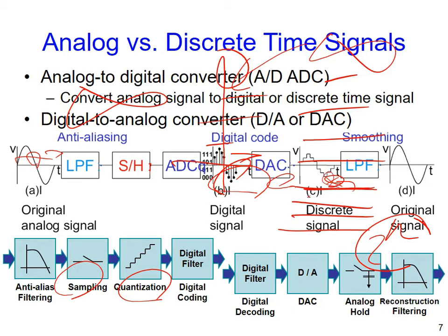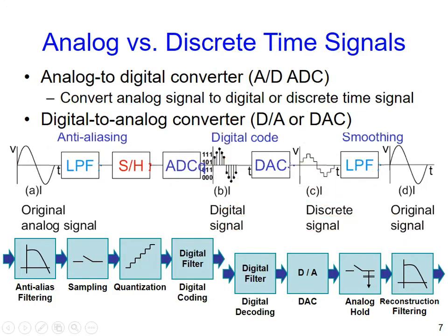That's it. From the bottom we have all zeros. For example, you have 3 bits, and then you have 0,0,1, 0,1,0, 0,1,1. Congratulations! This sample will be represented by 0,1,1. That is the very fundamental idea of quantization. After sampling and quantization, congratulations, you get the so-called digital signal. After that, you can do everything you like, just like encryption, 加密, compression, 压缩, everything you like.